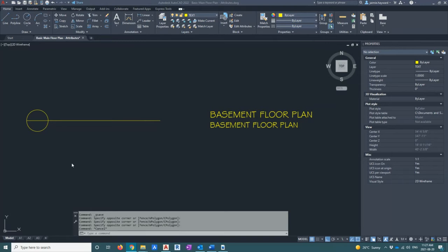Attributes are used for things that are commonly used, like a title block, or this view title, or let's say you use a certain logo that puts a project number in it, that you put on every single page of your drawings. Attributes are used, again, for something that you use a lot of.